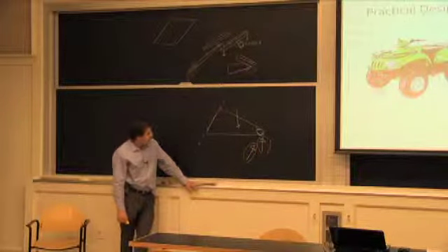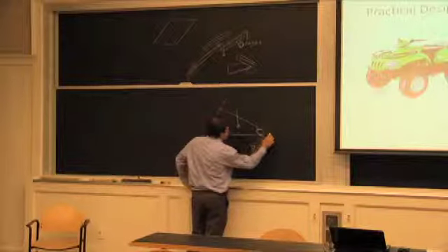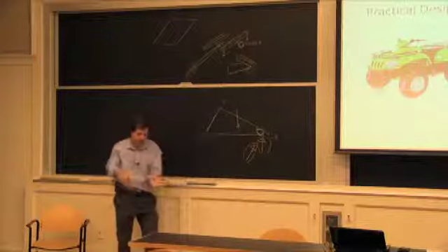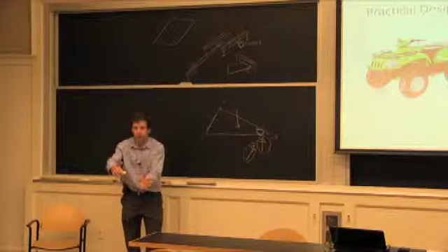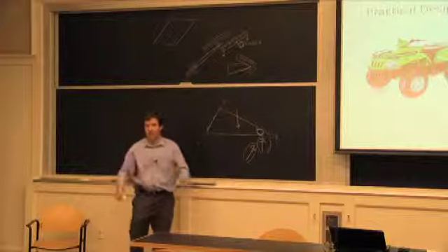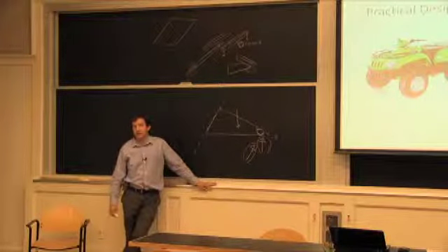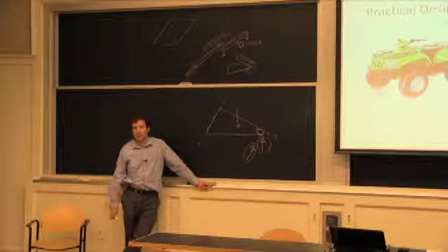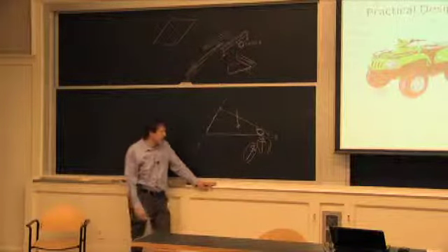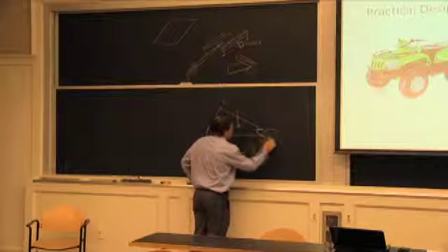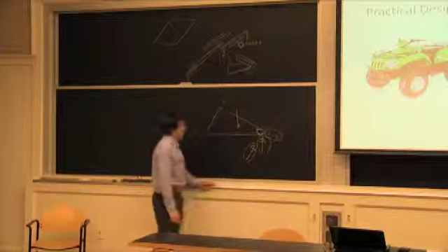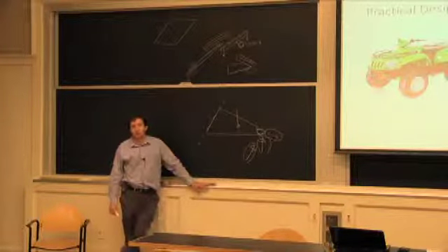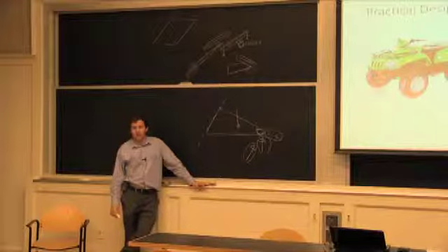And as far as a load this way from turning, it's a little bit the same story. If you turn your wheels, there's only so much you're going to engage with the ground. Maybe it's a friction factor of 1 in the worst case scenario, but most likely if you're on the road, it's going to be 0.6, 0.7 for rubber. So you can work out these 3 forces. I don't know exactly how you handle the question of hitting some stones and wood pieces.